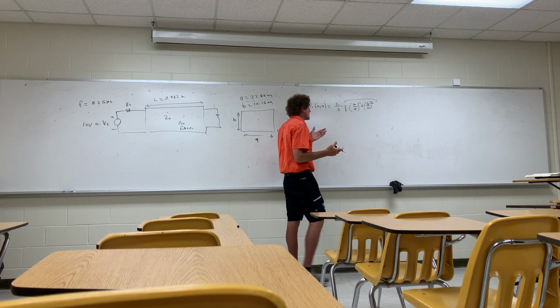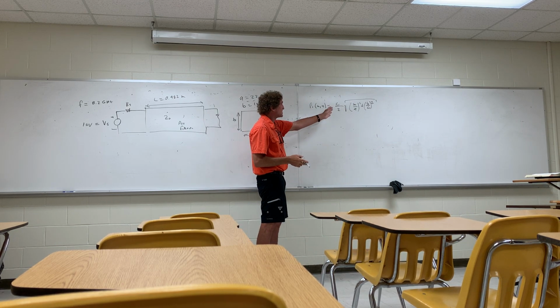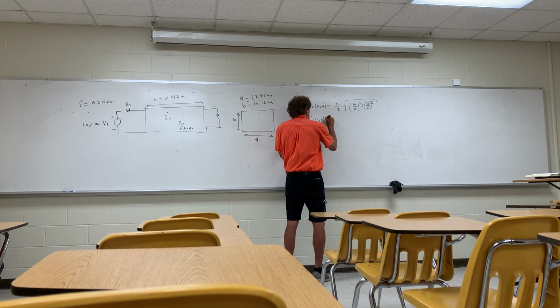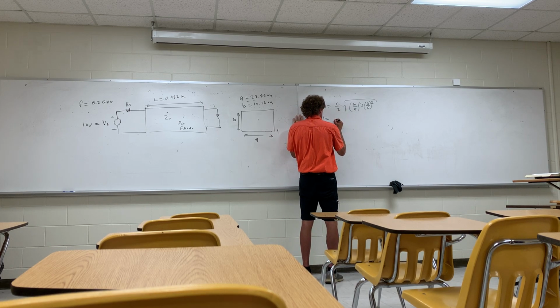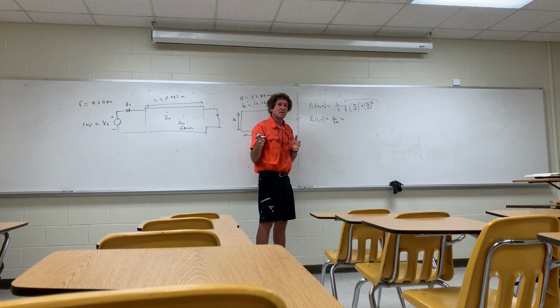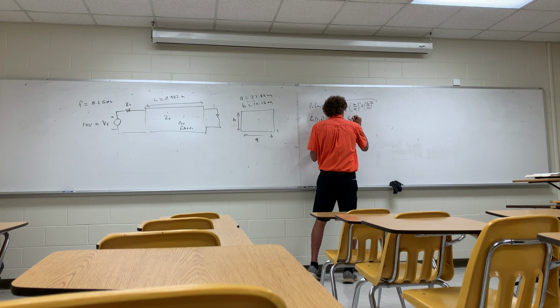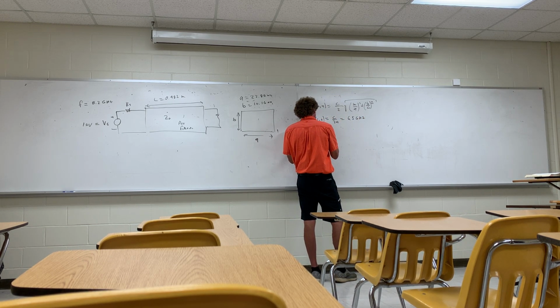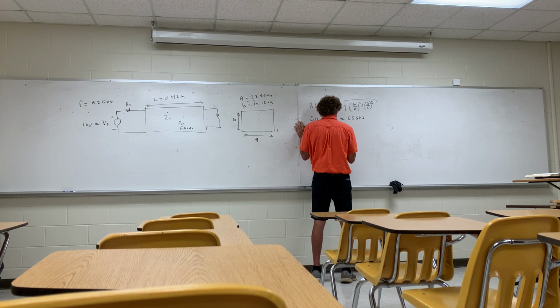Now this is straightforward. The only thing you need to do is make sure you have a square root operator and you're squaring things inside there. So you look at FC10, right? That really is just going to be c over 2a, and 3 times 10 to the 8, can somebody just give it, please? It's 6.5 gigahertz. Next one is going to be double that. FC20 is going to be double that, or 13 gigahertz, right? Yes, sir. 13 gigahertz.